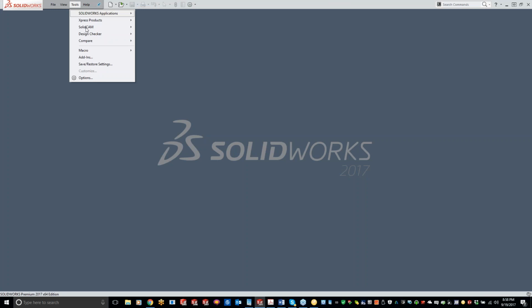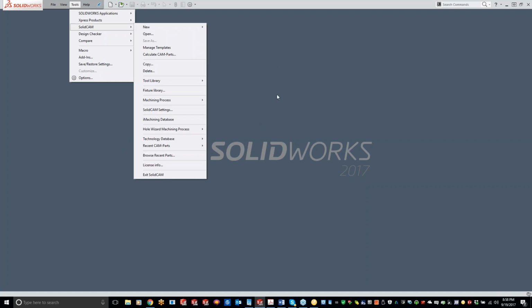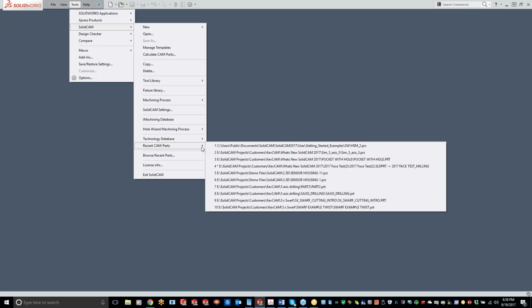It's still closing down that, and for those of you running with zip files, if you close out of a large file, you'll notice things will slow down for a second or two. What it's still doing is zipping up that project behind the scenes. If you're running in compressed mode, and I hope that you are, especially if you're working on the server, it eliminates a ton of lag time. Do compress, because it's everything saved locally. For those of you that didn't know that.